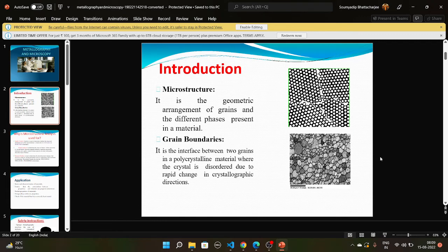In conventional machining processes, many forces arise in the X, Y, and Z directions. As far as I remember, the cutting force is tangential to the job as you cut it, and the thrust force comes in the normal direction on the tip of the cutting tool. The feed force is along the feed motion, the thrust force acts on the tool, and the cutting force is tangential to the cutting circle. Out of these three forces, cutting force is the maximum. Cutting force, feed force, thrust force: these are the three common forces arising out of the machining process.